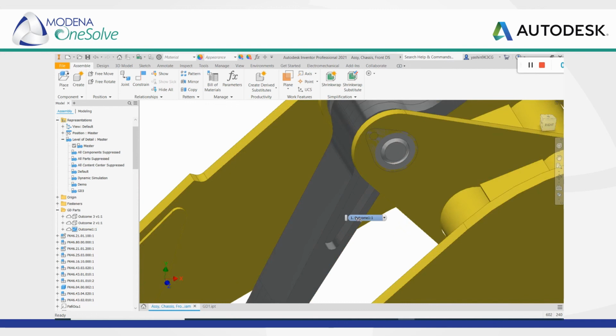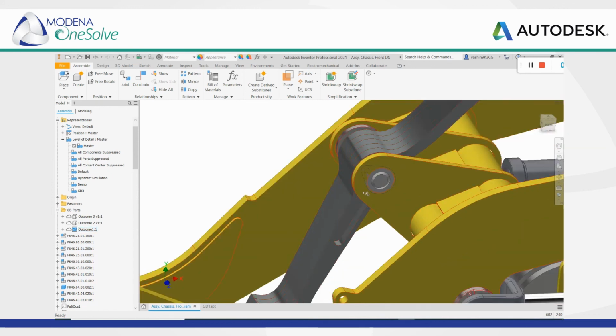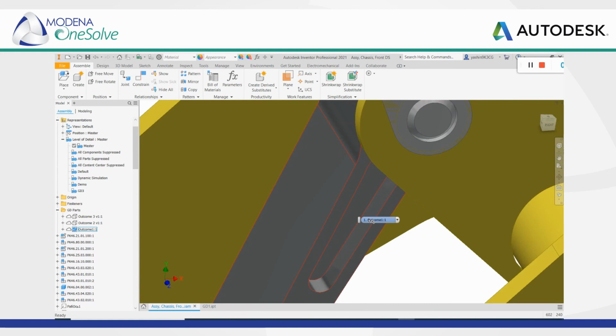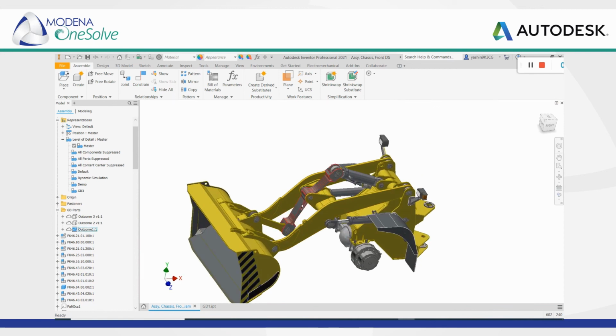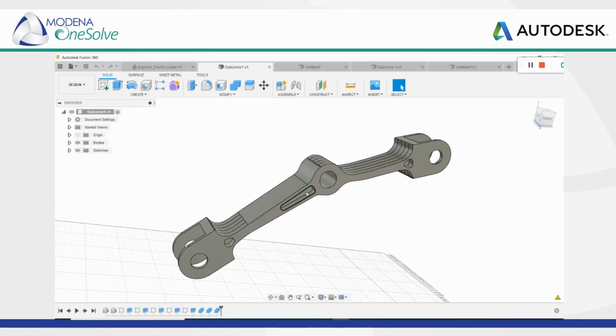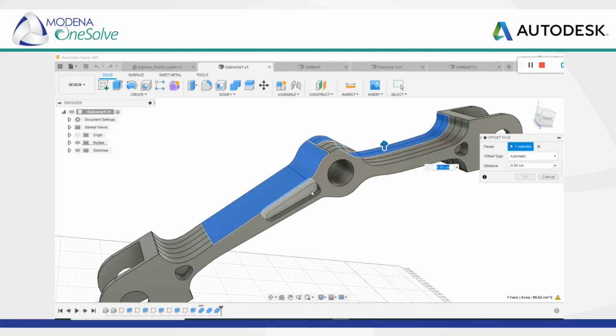Now, if you have a look, we've decided on this design and we'd like to make some changes to it. With this workflow, like I said previously, it's bi-directional, so any change made in Inventor will reflect inside of Fusion 360. So what we're going to look at is maybe we actually want to lightweight this component a little bit more. We find that we may have reduced the loads that are going to be subjected on it. So I can head over to my Fusion workspace and make those design changes very quickly. What I'm going to do is cut a hole through this component directly from Fusion 360, cutting all the way through this arm.